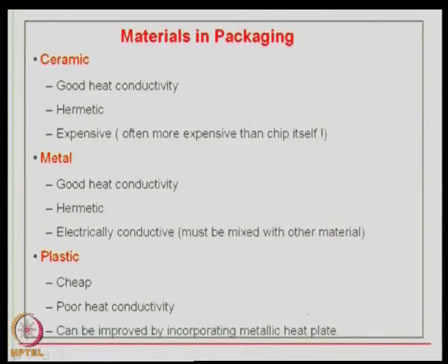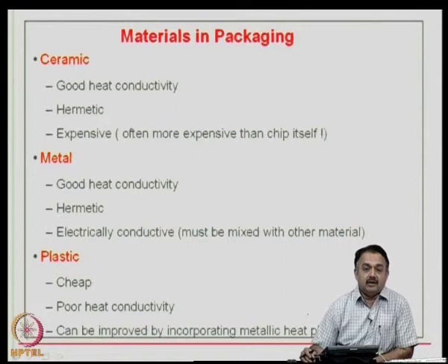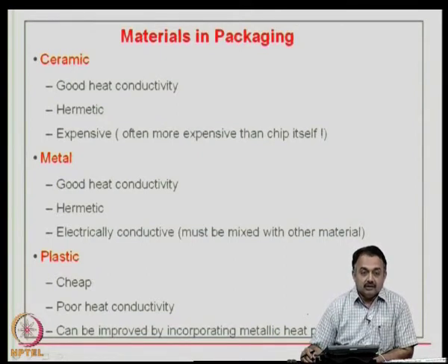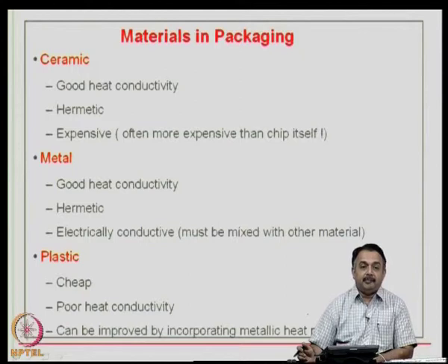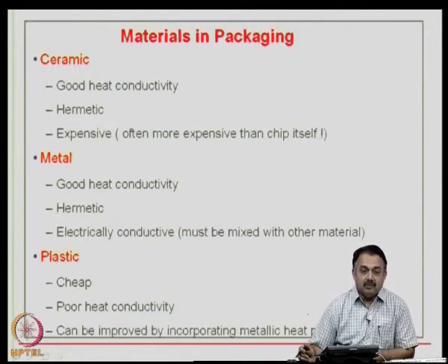So, therefore, you can see now that materials in packaging are very important. The choice of a plastic package or a ceramic package is again based on what you are expecting in terms of application. Therefore, all applications need not have a ceramic choice and all applications need not be plastic. So, you have to carefully look at the circuit that you are working with, whether it is a power or a communication circuit, or an analog circuit, what kind of simulations you have done, and what kind of heat requirements there are in terms of material choice.